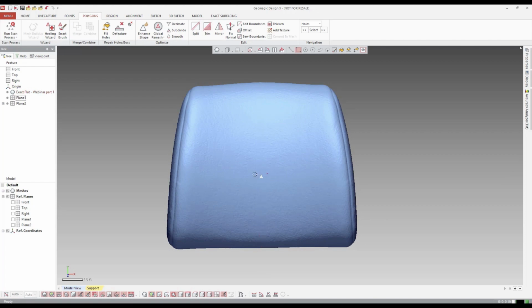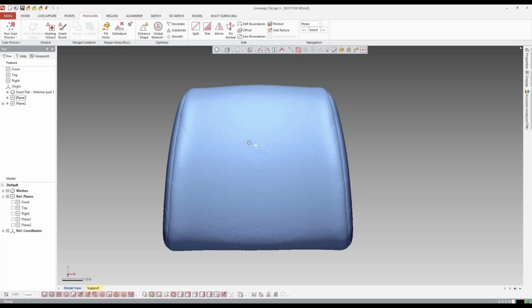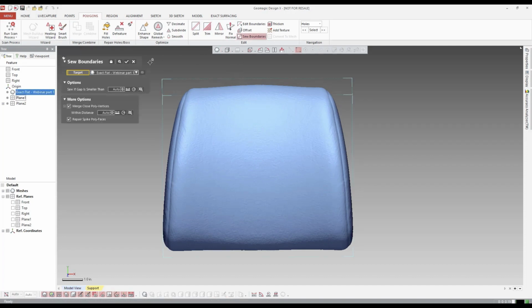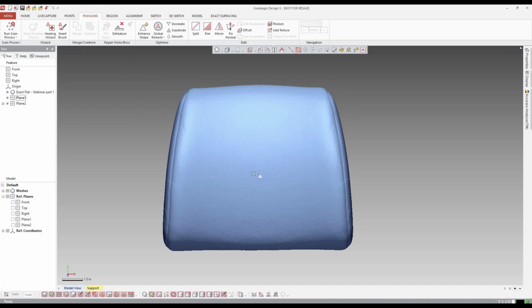We have a little bit of an area here where it was mirrored, where the triangles are not necessarily going to line exactly back up for the mesh. So what I'm actually going to do is hit sew, and it's going to stitch them together. Now you'll notice when I highlight over here, there's no real interface of boundaries between the two meshes.